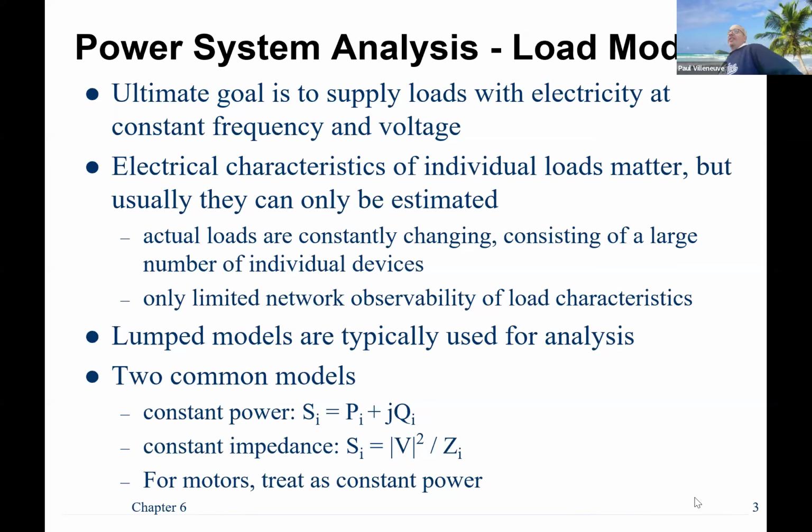So loads are being flicked on and off, right? You're turning your light switch on, you're turning it off, you're running your garbage disposal, your dishwasher, your oven. Sometimes you're doing that, sometimes you're not. So you don't necessarily have all the specific information about individual loads. So you aggregate them. You put them all in one lump, and then you define it as a P and a Q, or a P and a power factor, or an S and a power factor. And those are estimated typically for what we would do.